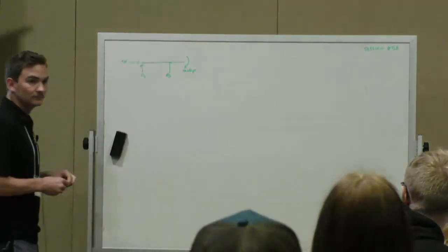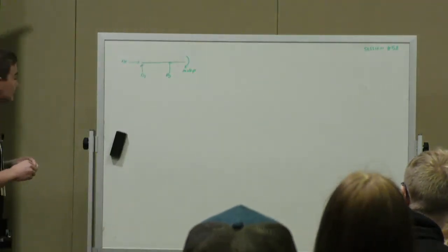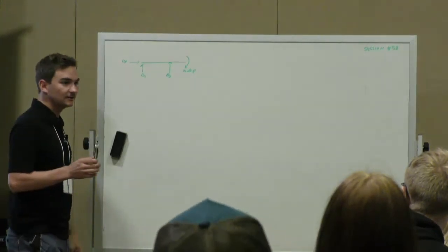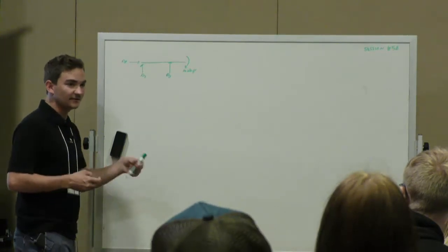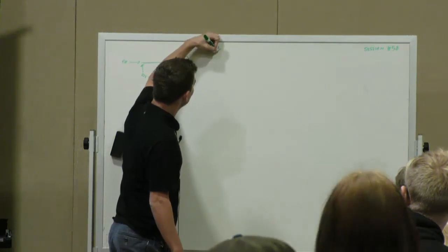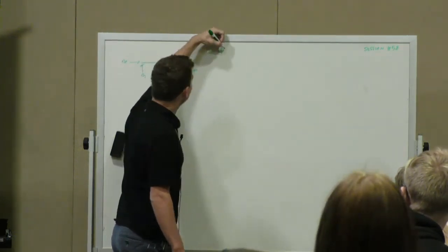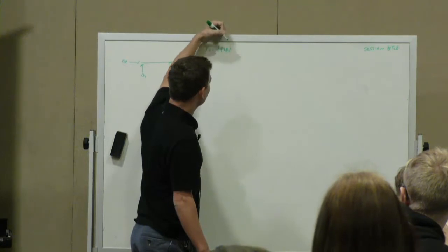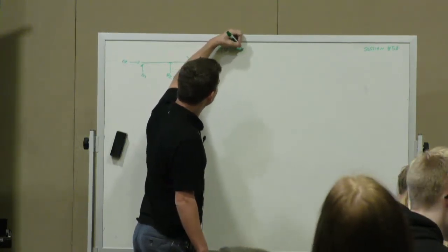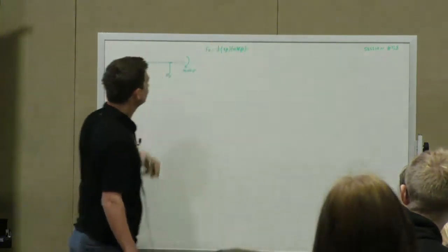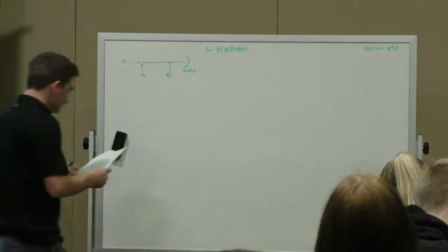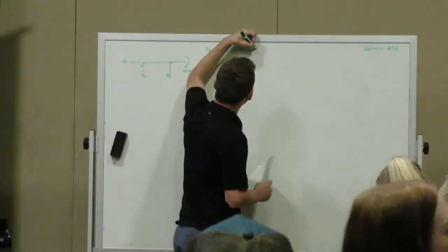There's a concentrated load 6 feet away from A. So how do we simplify that distributed load into a force? It's 1/2 base times height. So that's how we find our FR, the equivalent force. So 1/2. So what's the base? 9 feet. Very good. And what is our height? 50 pounds per foot. That's 4.5. And that comes out to 225 pounds.